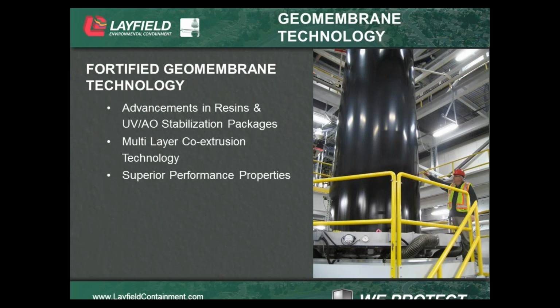But what we really try to focus on is a fortified geomembrane technology, which introduces advancements in resins and UV antioxidant stabilization packages. It utilizes multi-layer co-extrusion technology and superior performance properties such as multi-axial elongation, HPOIT, and other types of superior performance properties that make it more fortified than the standard industry grade geomembranes that are produced.